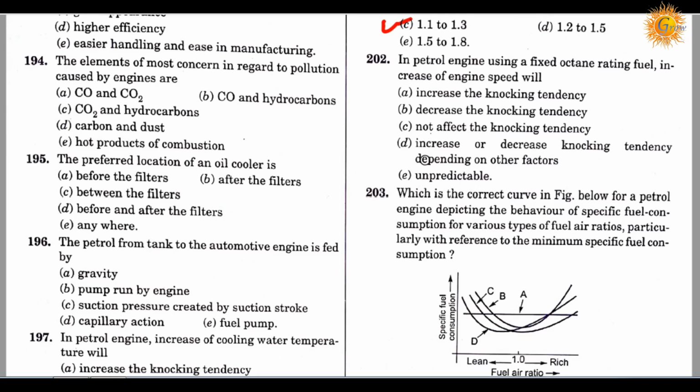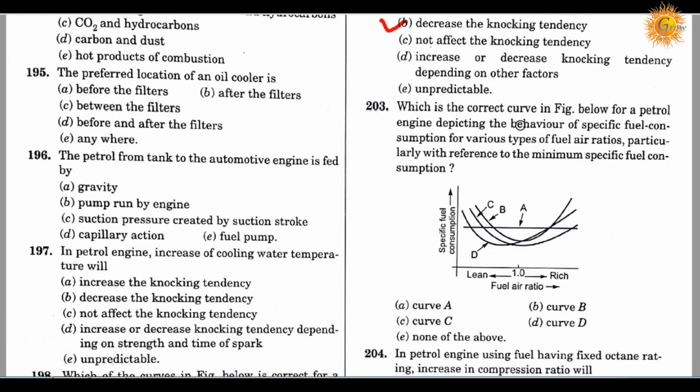So the correct answer is B, because in a petrol engine using a fixed octane rating fuel, an increase of engine speed will decrease the knocking tendency.